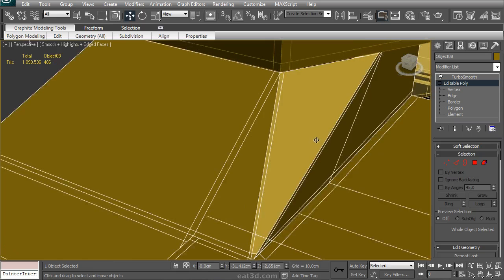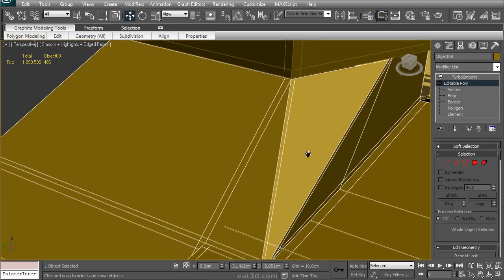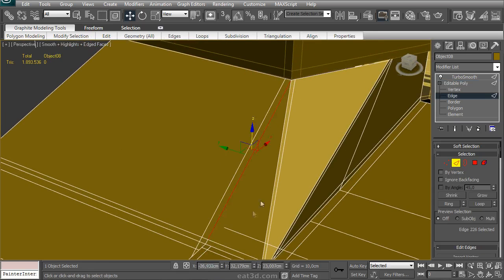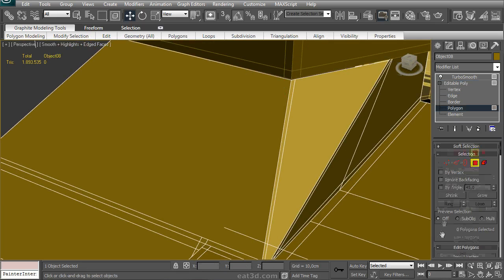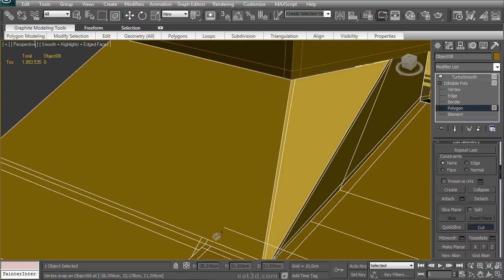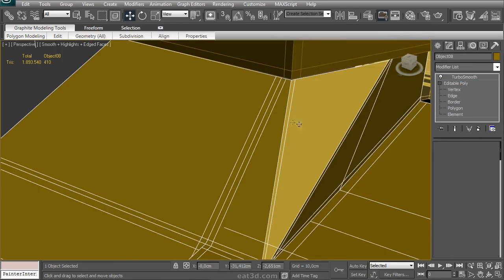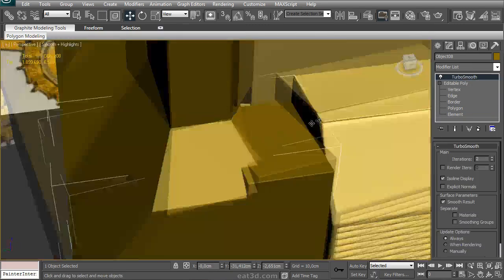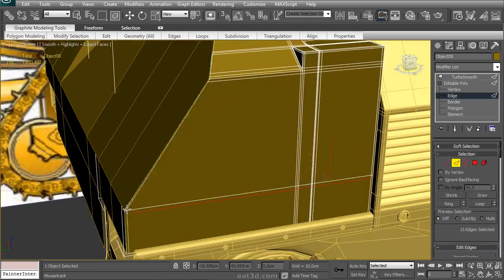And I can see why that is. It's because there's a triangle there. At the bottom we also have a bit of an n-gon, so we can just use those to cancel each other out. Selecting those, using the cut tool, cutting that up there, like that, and like that, and there we are. That part is fixed up.